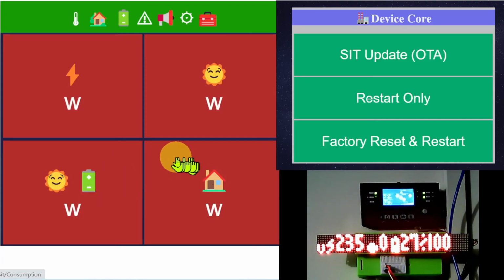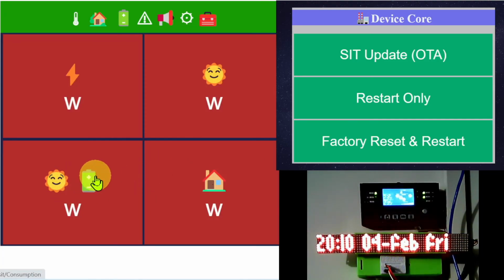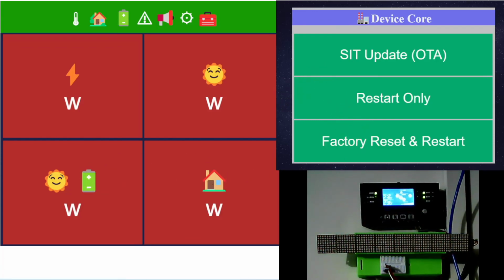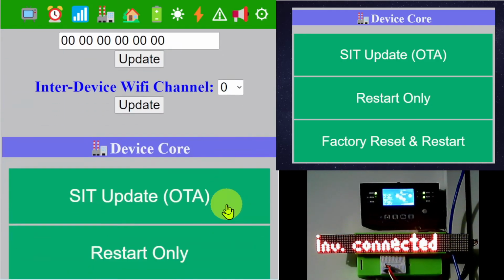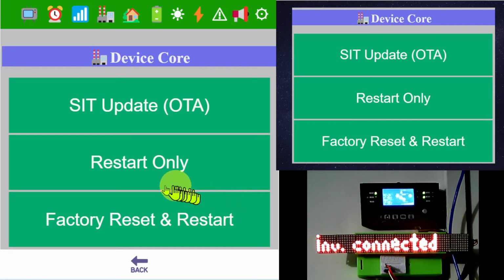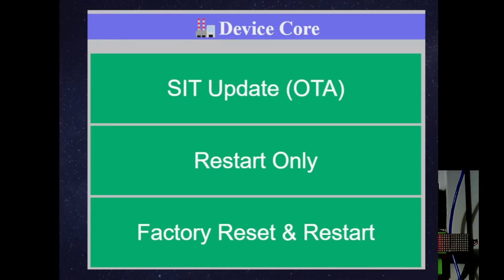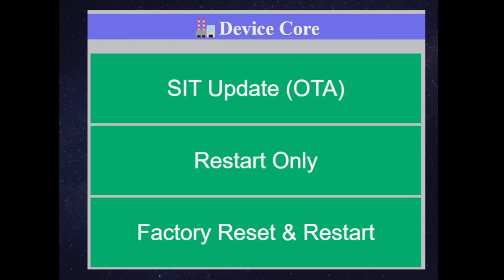If this reset doesn't work, you can attach the ESP with a PC and send a serial command: FactoryDataResetY. No spaces between these 4 words. FDR and Y in capital. If there is any change in setup, I have plans to do a follow-up video. Otherwise this guide will work.